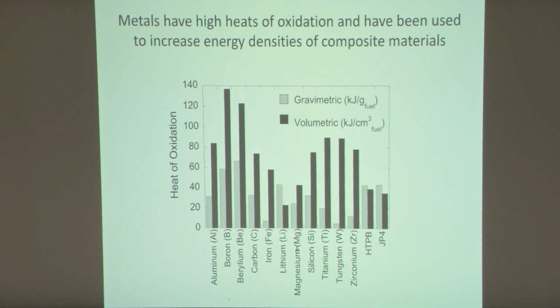I will talk a little bit about boron, but most of the discussion is going to be on aluminum because it's the more popular. Boron particles have had some difficulty in propulsion systems. And you'll see that in a little bit. They're very difficult to ignite, and to capture all of the energy out of the usage of boron, you've got to form certain molecular or condensed phase species in the products.